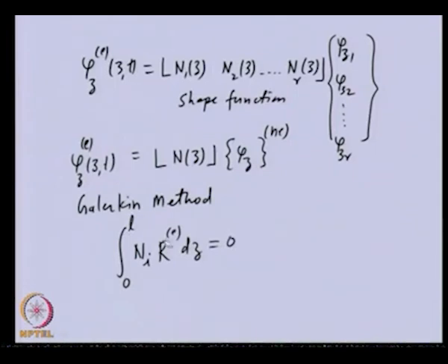So, that whatever the residual is there, that is distributed over the length. These shape functions are in number depending upon the degree of freedom of the element, so that many equations will be obtained from this method. Now let us see what is the form of the residual. The shape function we will at present keep in the general form, and subsequently we will be obtaining the explicit form of this particular shape function.